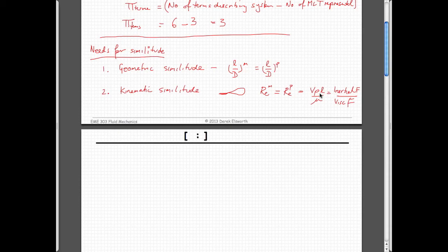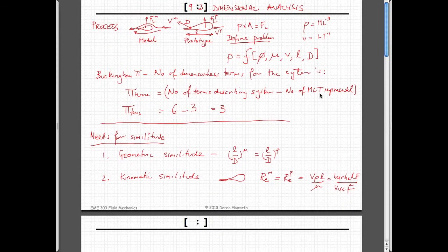And so actually, you could imagine that in our model, the other thing that we have, in addition to the shape of the model, which I'm not drawing very well here, is that we said we have a length, we have a span, and we also have another characteristic dimension, which we haven't mentioned: width. If you're looking at width, typically you'd think that the lift would be related to the planform area of the wing, not really the thickness.